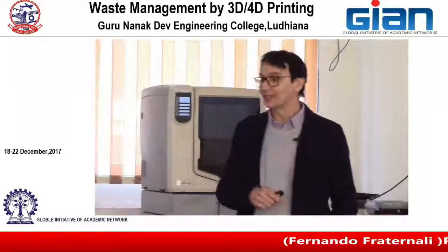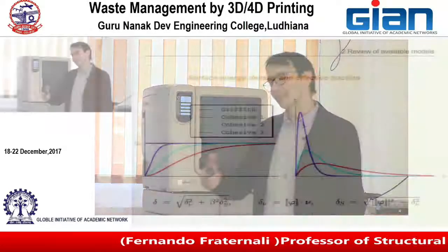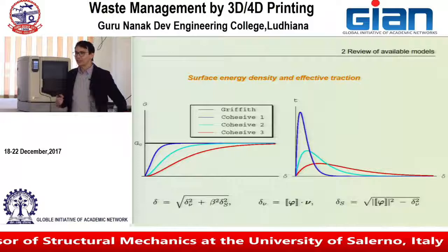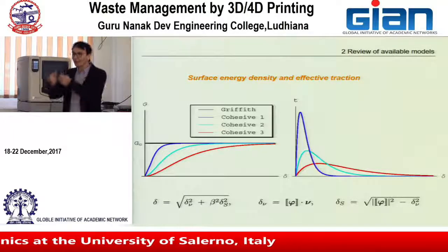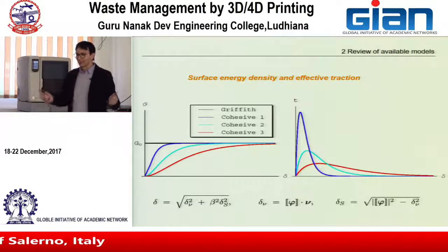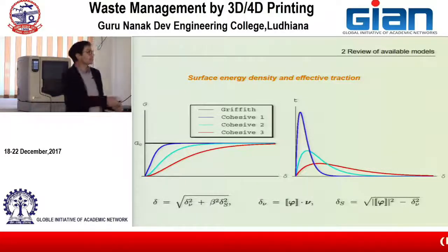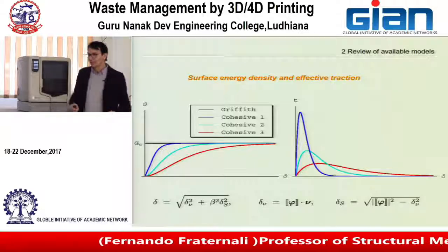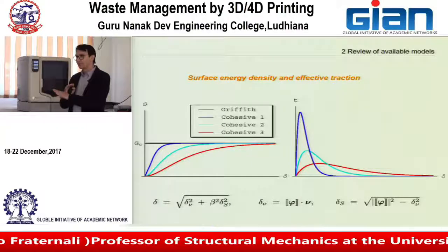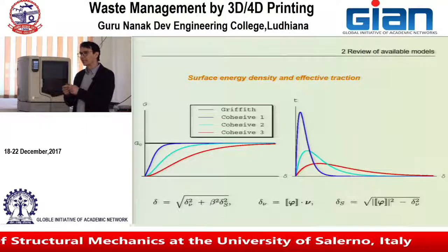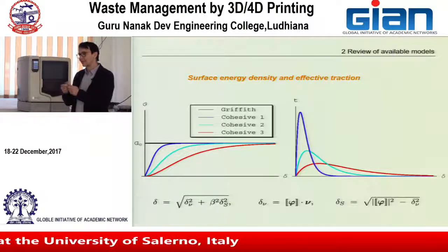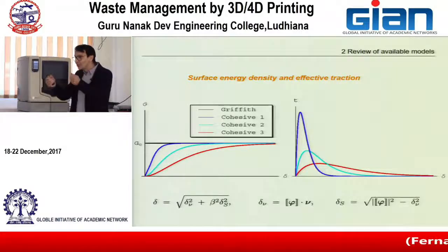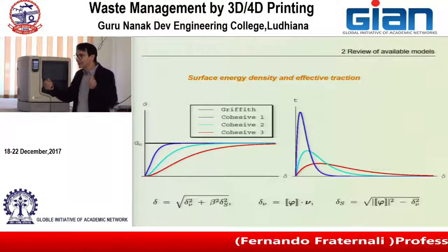what is the shape of the surface energy? There are several kinds of fracture. The surface energy is the energy that you have to provide to open the crack. It can be a constant, typical of the material, and that is the case of a purely brittle material. So the energy that you have to provide to open a crack does not depend on how much you separate the crack lips.